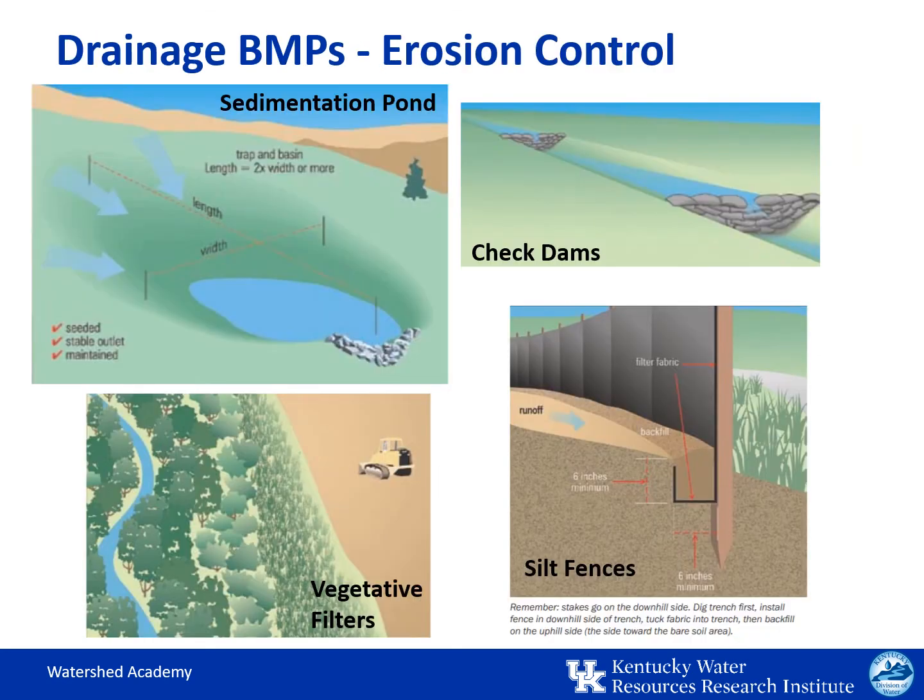This slide shows other erosion control measures that are used on mining sites and common to general construction activities. From the top left, we see sedimentation ponds, which are water detention storage structures designed to detain storm flow. These enable the removal of settleable solids from runoff and collect runoff flows for point source discharge. They should be located immediately below the disturbance and out of perennial streams unless otherwise approved in a permit application.